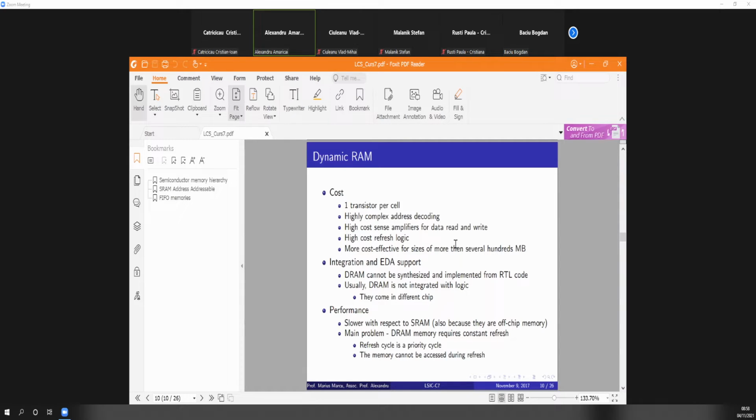So you are not performing the refresh within the 0.6; you're performing it at, let's say, 0.8, which may not be enough for the refresh, and data will become corrupted. So the DRAM has this lower and higher frequency range.